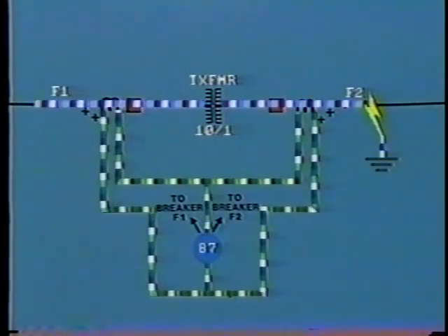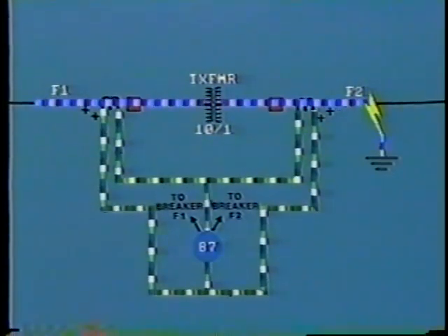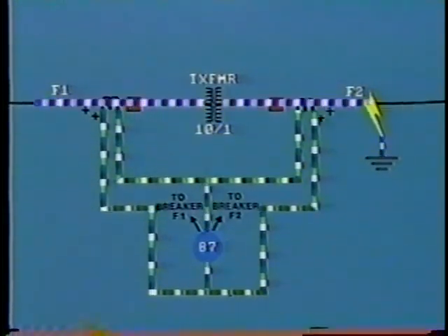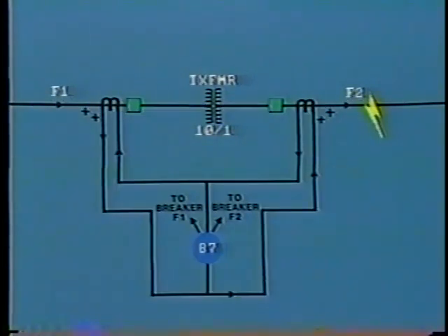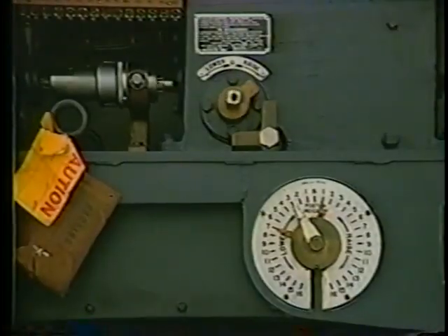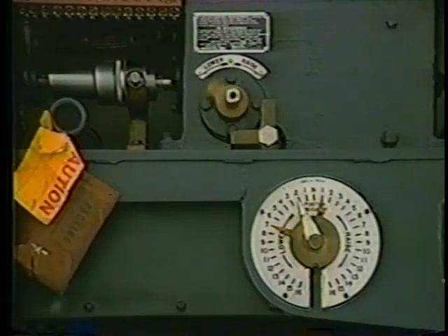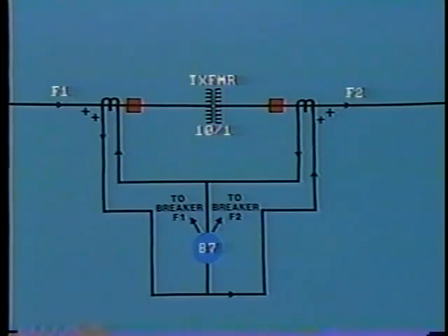However, things may not be so comfortable where we have an external fault which causes a high current to flow through the transformer. In this case, the CTs will be measuring a balanced condition, but the error will be magnified and may cause the relay to operate. Similarly, transformer tap changers introduce problems with CT ratios. In order to avoid these problems, restraint coils are normally fitted to the relay.